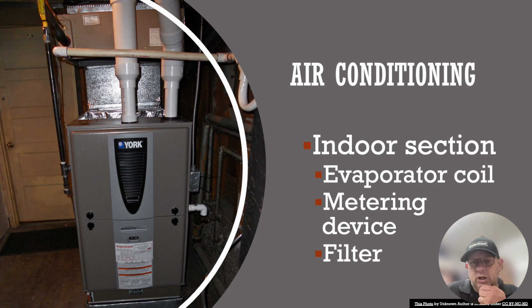Now, there are certain pitches that we have to have the drain line at, and a good rule of thumb for that is every foot you should be dropping a quarter of an inch for your drain lines to drain out properly. You do not want to drain your drain lines out too fast, otherwise sediment would end up in those lines and stuck in those lines as well.